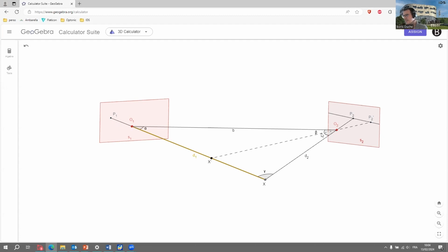So you know the baseline, you know the vergence angle, but try to imagine if that moves a little bit, from the production to the delivery of the camera to your place. I don't know, there is a shock onto the camera, and the vergence angle slightly moves. Then this value that we use to compute the depth is not accurate anymore. This is why in our stereo cameras, the chassis is made in aluminum. We are very experienced in making these cameras, and the calibration is not lost. That's a very important step that we will discuss in the next chapter of this video.